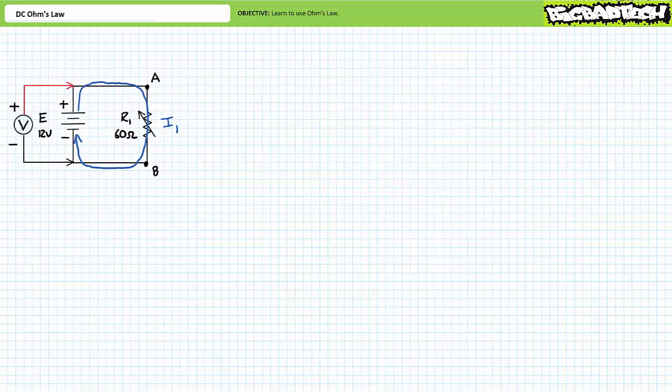When measuring the voltage rise induced by an active element, like a voltage source, a voltmeter is customarily employed such that the black reference or common lead is on the negative polarity marker and the red lead is on the positive polarity marker. Let's say the single source in the circuit, E, induces a voltage rise of 12 volts. A voltmeter configured in this fashion would read 12 volts.